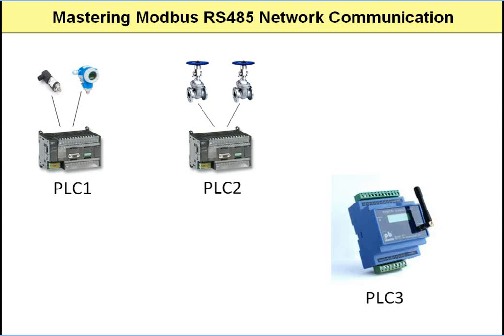Our problem then is to connect PLC3 to PLC1 and 2 using RS485 and then configure all three PLCs so that PLC3 constantly reads the latest values of pressure, temperature and valve positions from PLCs 1 and 2. PLC3 then, having these values, will transmit them periodically back to the marine base for data capture and analysis. So that, folks, is the problem we're going to solve at the end of this course. From here on, as we go through the theory and practical details of Modbus and RS485, I want you to constantly keep in mind the problem that we are trying to solve.